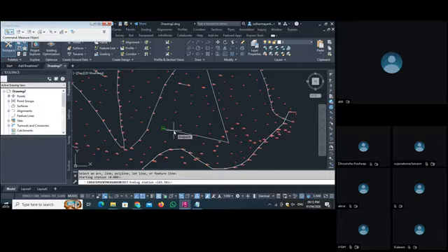I want to keep our station as provided, so end here. Then it says specify the offset, so I want an offset at every 10 meters or every 100 meters, whatever it is. I can select this, and then it will ask us the interval. Let's keep it. Enter a point description, our borehole.